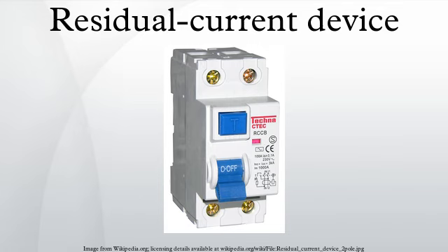In the case of RCDs that need a power supply, a dangerous condition can arise if the neutral wire is broken or switched off on the supply side of the RCD, while the corresponding live wire remains uninterrupted. The tripping circuit needs power to work and does not trip when the power supply fails. Connected equipment will not work without a neutral, but the RCD cannot protect people from contact with the energized wire. For this reason circuit breakers must be installed in a way that ensures that the neutral wire cannot be switched off unless the live wire is also switched off at the same time. Where there is a requirement for switching off the neutral wire, 2-pole breakers must be used.